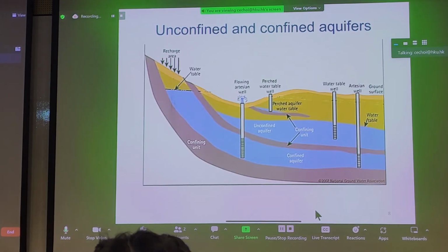Why is it important to consider total head? Because there are circumstances where, if you recall, there are unconfined and confined aquifers where you would actually see the water level even come out of the ground, exceeding that of your instrument, your piezometer or your standpipe. Now, if you look at these instruments here, these represent tips of instruments. I'm guessing these are piezometers here. And if you look at the geology of this particular diagram, it's quite interesting.